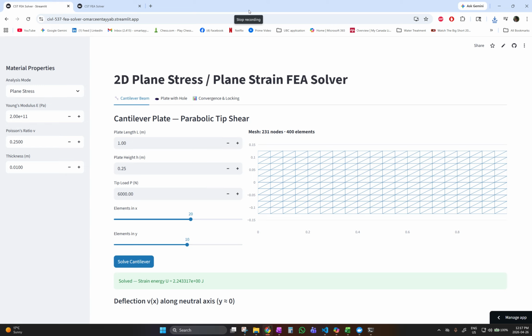I hope to answer the rest of the questions in the viva. But what I tried to focus on is the physics of the problem and some things we want to be careful of to get meaningful results, like the ratio of the applied stress to the elasticity. Why we don't get the peak hoop stress at the exact location is how we approximate the hole, versus how the stress decays as we move away from the hole, because the material initially has the traction free boundary condition at the hole.